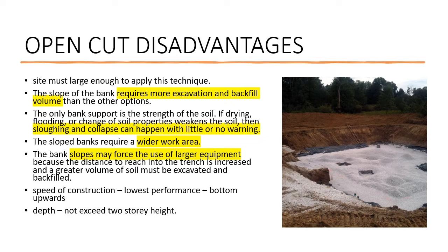The slope banks require a wider work area. The bank slope may force the use of larger equipment because the distance to reach into the trench is increased, and a greater volume of soil must be excavated and backfilled. Jadi you need bigger machineries, bigger excavators untuk move around because you need to move a lot of soils and kena ada backfilling process juga.